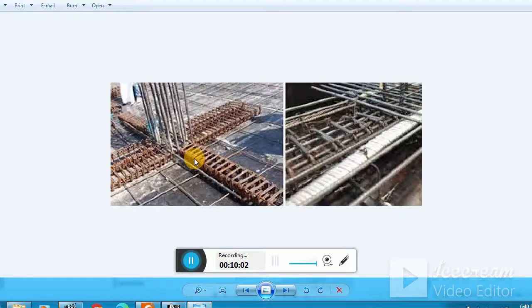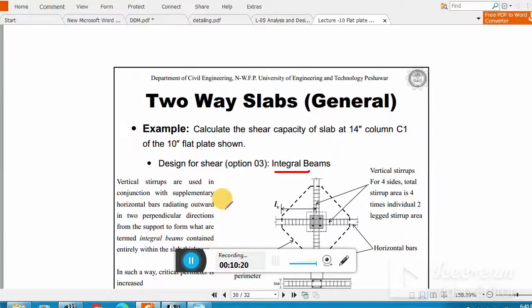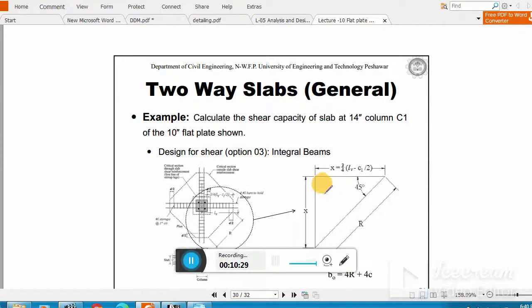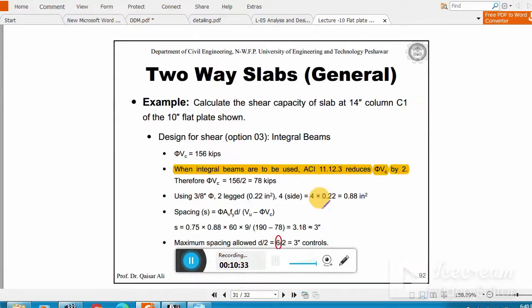In this ceiling beam, we basically have to determine the leg length of this beam, or you can say the length of the horizontal bar, and the design of the vertical stirrups, just like a shear design. So we have to find this horizontal length and this shear reinforcement. Clear? For that purpose, you already know we use this equation, and the equation we already derived.